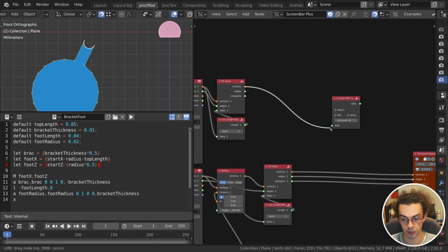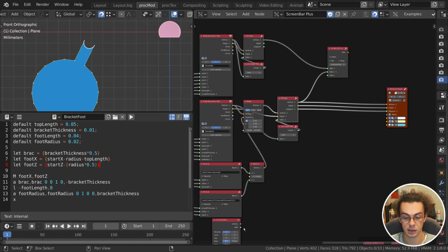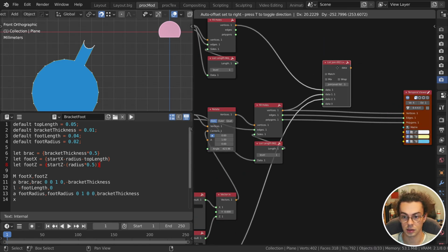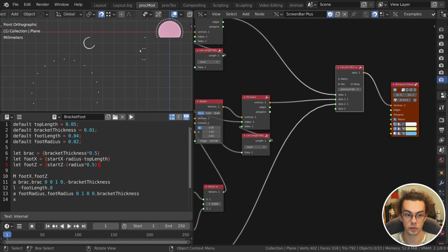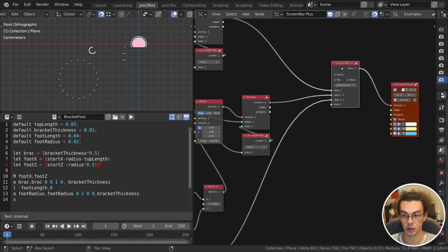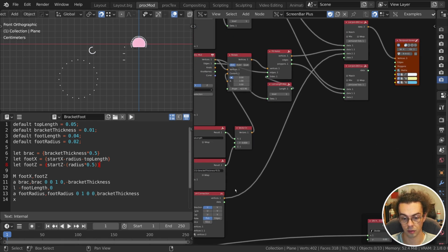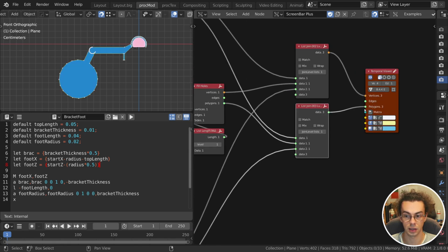So I'm going to connect the first one, the second one. These are of our parametric profiles, the actual bracket. And then the clip comes from our UV connection that we made before. So that goes in here as well. Don't need to change any of these settings. This is all fine. So you can see that we've got all of our vertices now showing. We just need to join up the polygons. So I'm going to take the polygons in the same order from each one of these. So the two fill holes and then the data from the UV connection. See that when I join this into here, into polygons, now we have all of those edges.